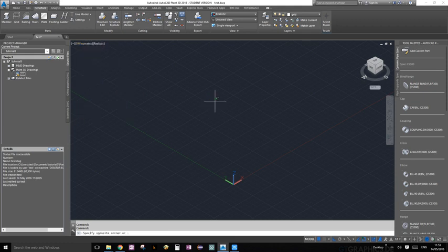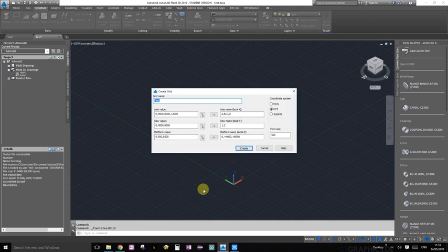Now we're going to press the grid button under the parts section of the structure palette. As you can see, this little pop-up menu shows up. Here we're going to set the axis values. On the local x-axis, we're going to have a grid line at 0, at 4,000, so 4 meters, 8,000 and 12,000. So we're going to have three little sections there.